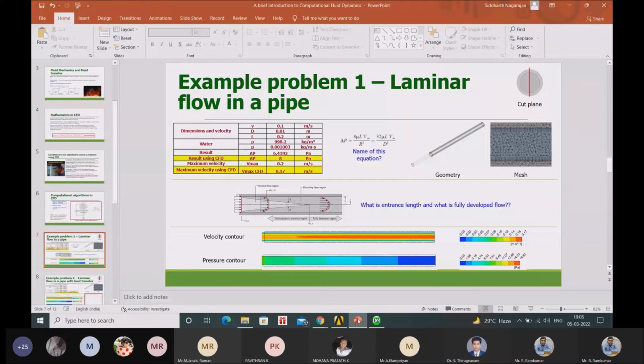So it's basically where the velocity profile becomes fully developed, from the region of developing flow to fully developed flow. So a parabolic velocity profile for a circular pipe is when the entrance region is fully complete. What will happen is at the inlet, you will have a uniform velocity profile, meaning wherever you check the velocity, it is going to be the same. So suddenly, if it comes in contact with the pipe, the velocity near the wall will become 0.